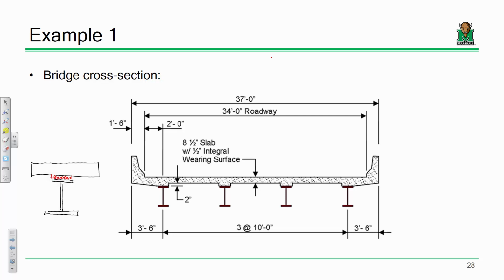Does that make sense? Another thing that you're going to have to account for when you do loads is not just the deck and the haunch, but you also have to account for this little triangular overhang taper. You have to account for that too, okay? Because that comes from essentially your overhang brackets that are used to form the deck. You'll usually have something that sticks out about like that and sort of juts into the exterior beam about like that.